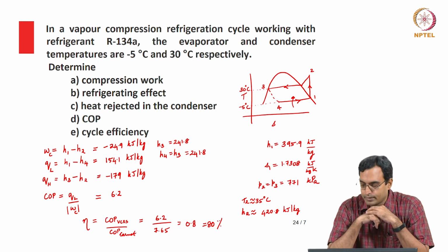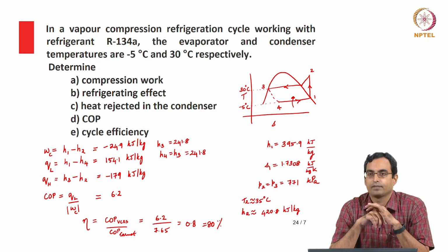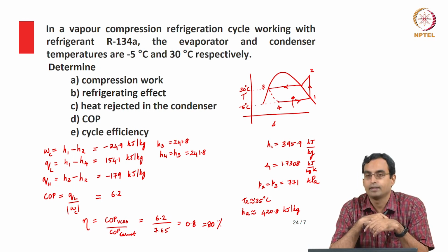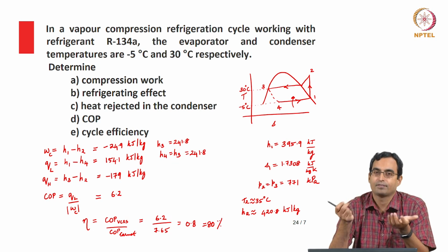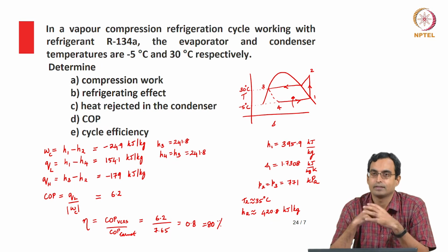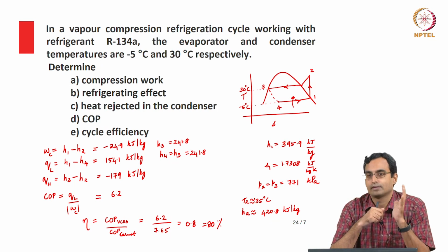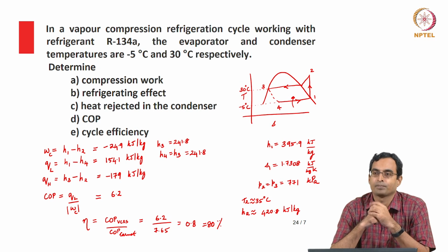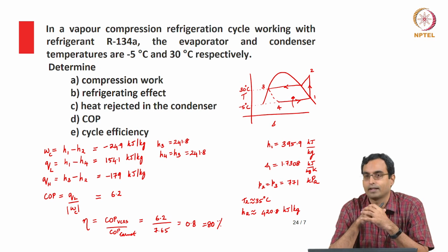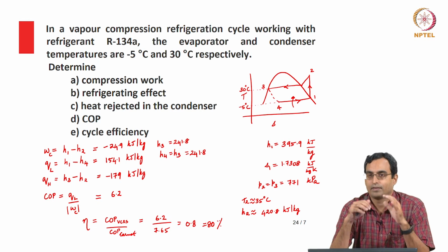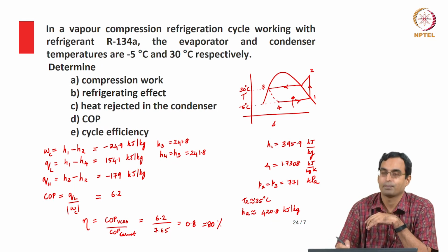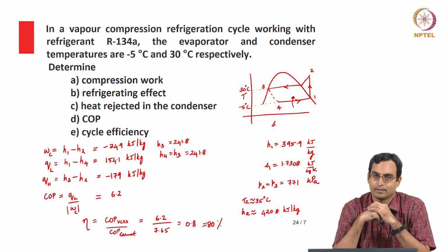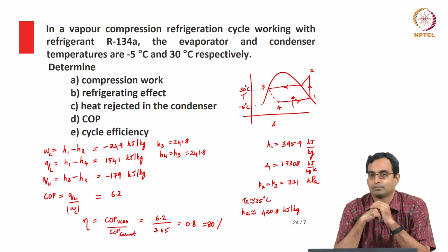So, what we see is that the Carnot cycle itself gives us some COP which is less than infinity, and the VCRS cycle says that you can't even reach that. Carnot says you can't get an infinite COP, you have to do some work in order to transfer heat, and that is the maximum we can possibly have. But the VCRS cycle, because of the way in which the cycle is constructed, says we first of all have a limit of Carnot, but we can't even reach the Carnot, we only get about 80% of what we could have got with the Carnot cycle, and this is a theoretical maximum.